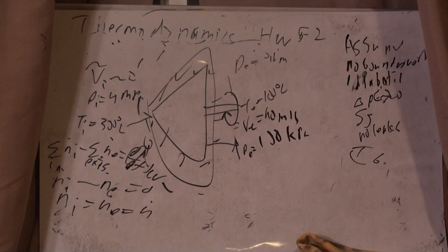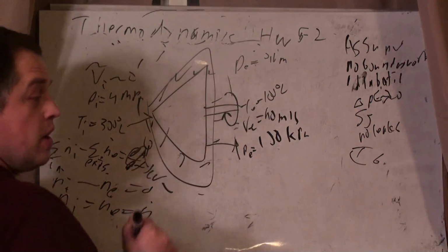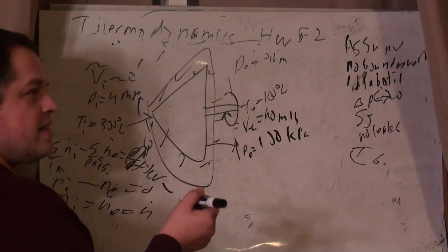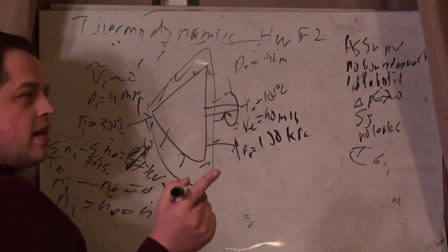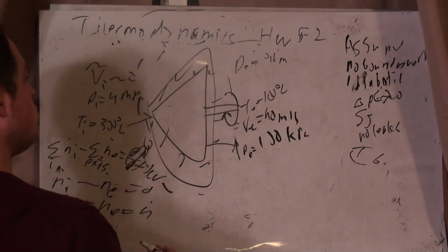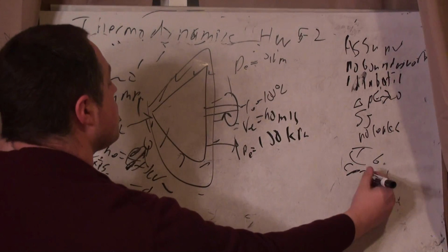Now, there might be some other assumptions in there. I would want to assume heat capacity is constant, but it didn't say heat capacity is constant, so I'm not going to get to assume heat capacity is constant. But I want to. And I think in this case, for this analysis, I'm going to. Last analysis, I didn't. Of course, last analysis, I also didn't assume it was an ideal gas, and I should have. So we're going to assume the heat capacity is constant just to keep the math simple. Cp is approximately constant.